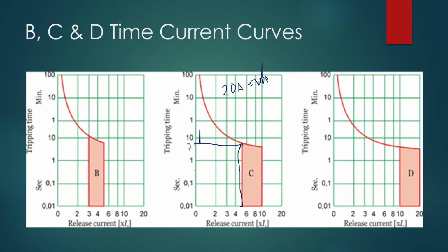So why do we need to understand these curves? Well, sometimes we connect the circuit breaker to a motor load, let's say an air conditioner. Usually air conditioners have inrush currents, which is a spike in the current at the start when you start the load, and this starting current is very healthy. We don't really need to interrupt that spike. So we will select a breaker, either a C-type or a D-type, and that is because it gives us a delay in time.